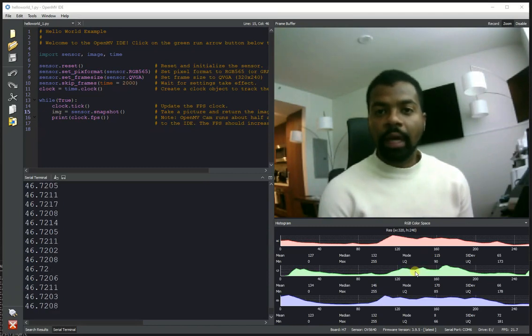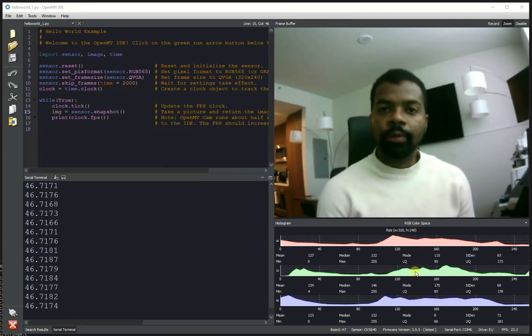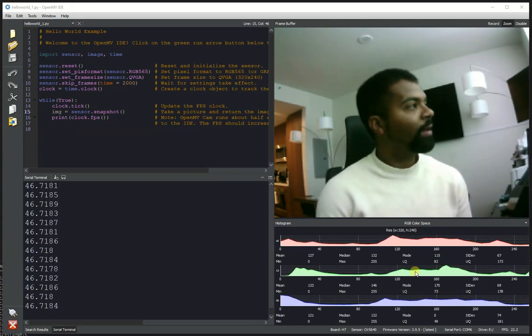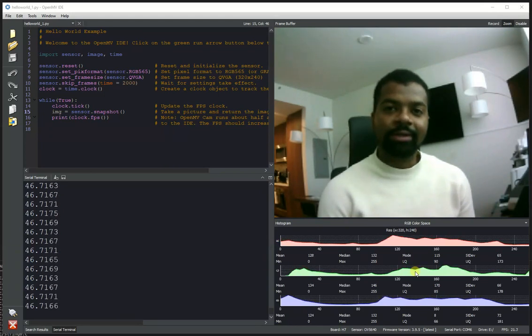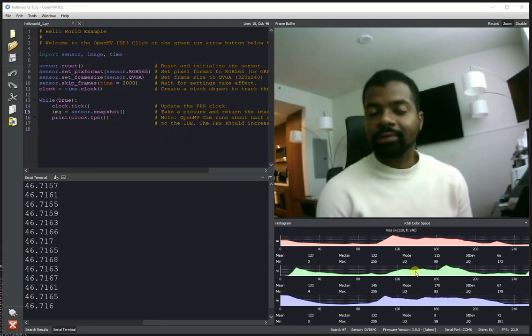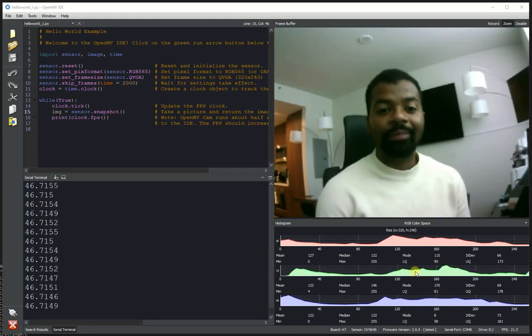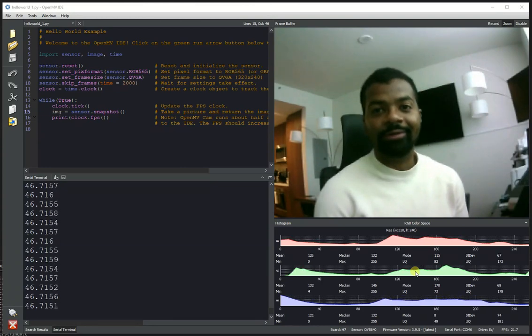We've recently been updating a lot of things on the firmware, and we finally got triple buffering and double buffering with the camera image capture working, which unlocks us to have the Wi-Fi shield operating in the background now without stealing performance from the image capture driver. We tried to release this feature about 3 years ago and it never worked quite well. And so we finally got back to it, and now we have really good Wi-Fi debugging support operational, and so I'm going to show that off in this video today.